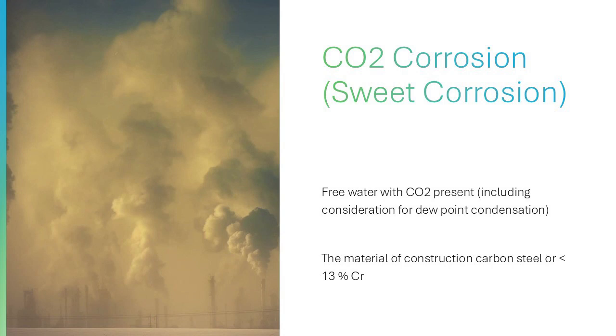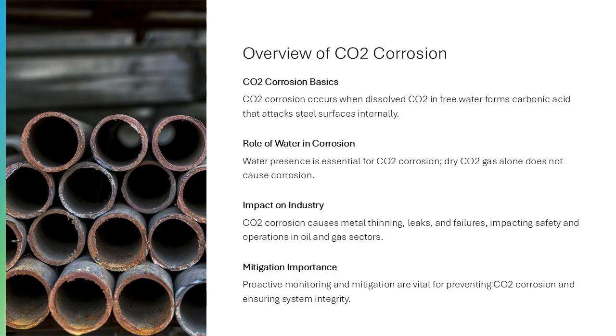CO2 corrosion or sweet corrosion. CO2 corrosion, commonly known as sweet corrosion, is a critical issue in oil and gas operations, particularly affecting carbon steel and low-chromium steel components. This type of corrosion occurs internally within piping and equipment when free water containing dissolved CO2 is present. The process begins when CO2 gas dissolves in water, forming carbonic acid, which lowers the pH and aggressively